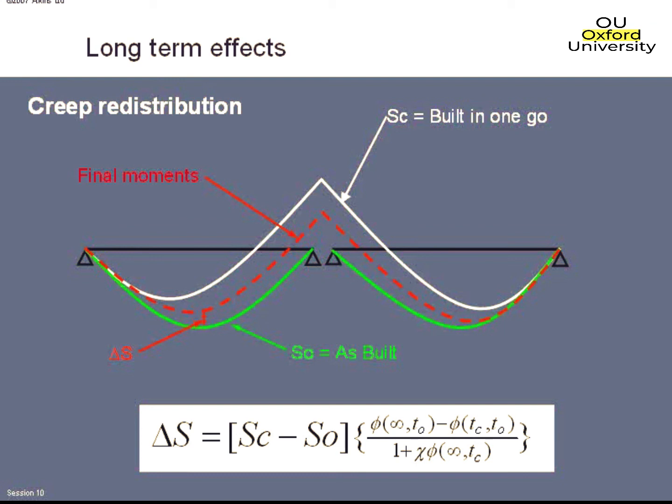The normal situation with pre-tension beams made continuous is exactly the upside down version of this, in that we normally put in far more pre-stress than we have dead load. So rather than creeping downwards, the beam creeps upwards. And therefore, rather than generating a hogging moment at the support, we create a sagging moment at the support. And various people have written papers about the need to put in reinforcement in the soffit, at the bearings, to prevent splitting going on there.